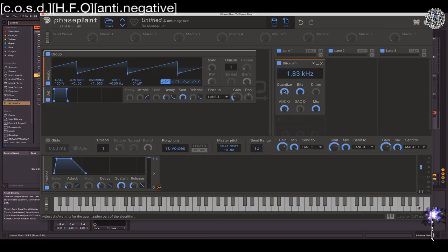Okay, so we have quantize, which is the step value of our waveform. Bits also correlate directly to that. The more quantize, the harsher the sound is going to be. Bits, remember bit depth: with a smaller bit depth, almost no dynamic range, and it will clip off to 0. Quantize is probably the least audible thing because it really is talking about the sample rate. Then we have dither. It adds noise to the signal in order to reduce the distortion caused by quantization errors.